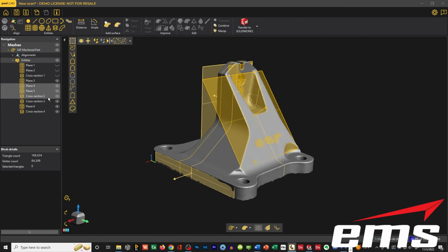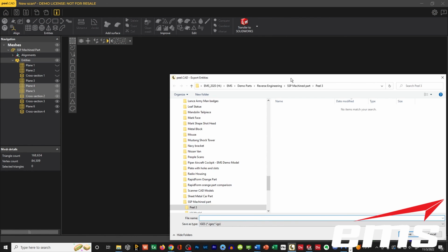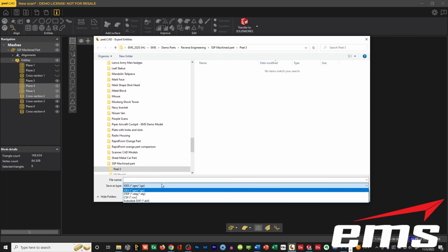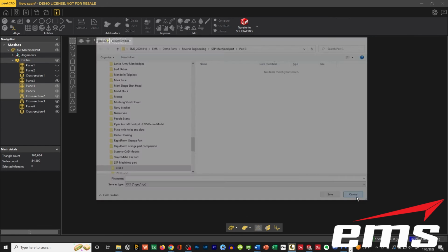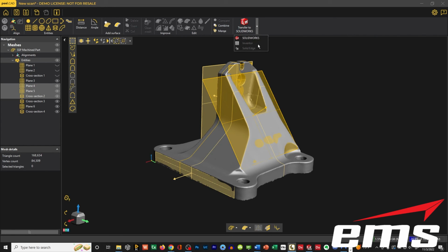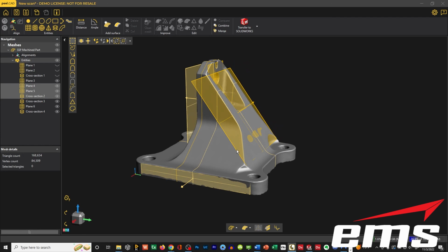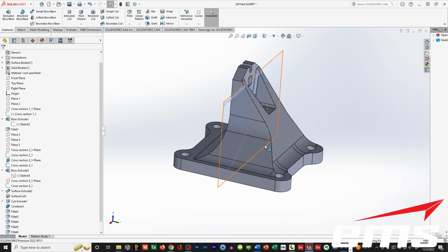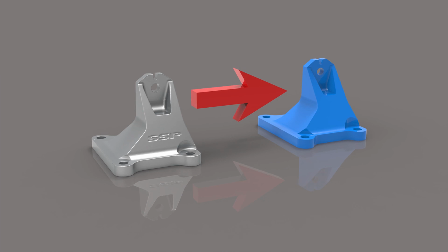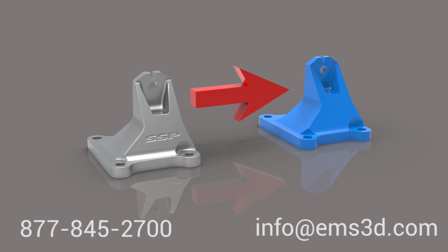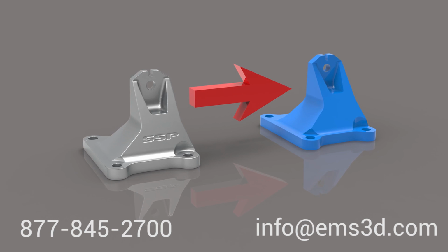With a different CAD system, you would select it, you would right click selected entities, and then you would pick IGES, STEP or DXF. That's really for just like lines. So it's just a little more automated going to these three systems. These are all Parasolid based systems, so that makes it easy. But that's the general process. So 3D scan, extract geometry off of the scan data here, and then into your CAD system, and then start building.